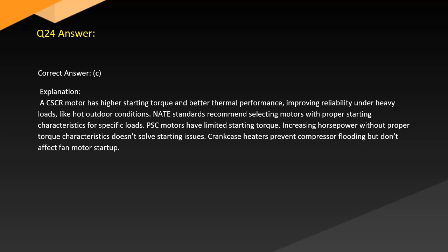Answer. Correct answer: C. Explanation. A CSR motor has higher starting torque and better thermal performance, improving reliability under heavy loads like hot outdoor conditions. NATE standards recommend selecting motors with proper starting characteristics for specific loads. PSC motors have limited starting torque. Increasing horsepower without proper torque characteristics doesn't solve starting issues. Crankcase heaters prevent compressor flooding but don't affect fan motor startup.